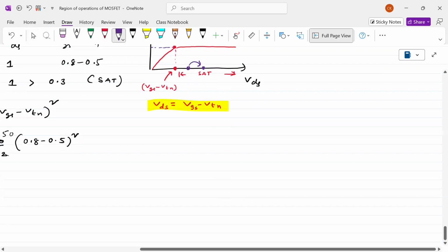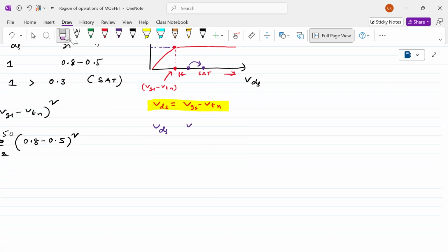This is simple, right? From here we can say VDS, here the source we can remove. Why? Because the potential is the same for the left side and the right side. VD is VG minus VT. Therefore, this is called VD plus Vtn. Here we can write VG. If this value is less than, that means the VG value is more than whatever the drain potential is. Just one threshold above it is sufficient.